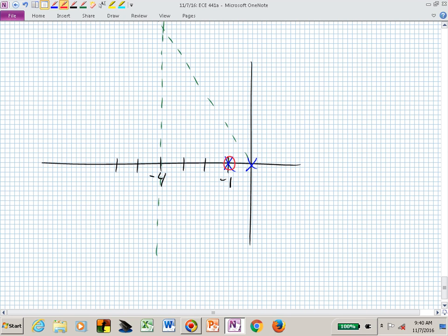And what do we know about a two-pole behavior's root locus? It's easy to sketch, isn't it? They come together and they break away at the exact midpoint and then they leave. And where they break away is halfway between the two poles. So if we want that halfway between to be to the left of -4, we now know where our other pole of the controller needs to be located.